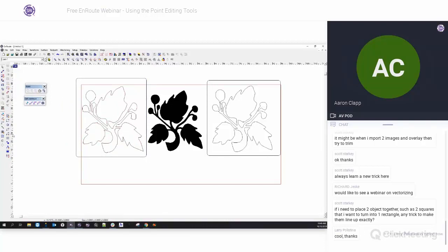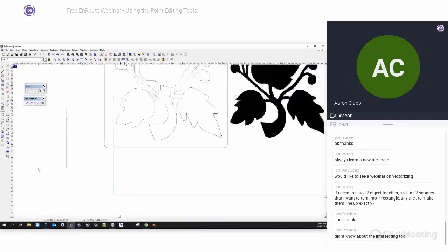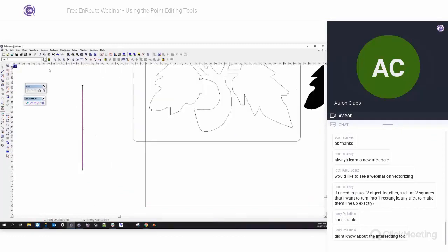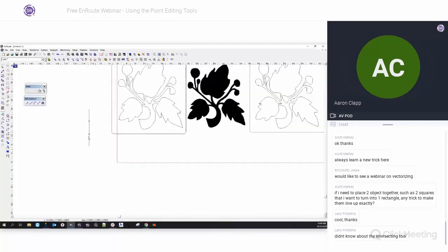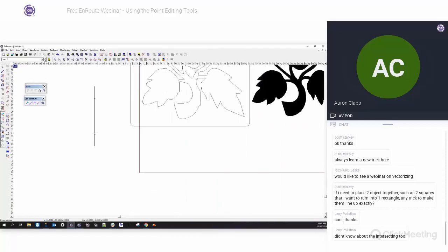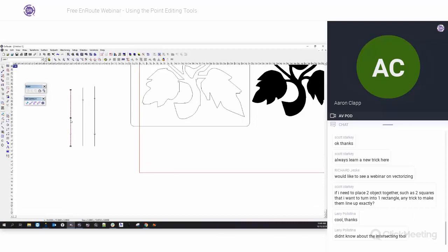Oh, and then the last one, there is another instance where this might happen. So if we have a line, just to say a line like this, I'm going to copy it and then paste it right on top of each other. And then I'm going to change the direction of one of them. This will happen very frequently. So anytime you have an open contour, you are only going to see one chevron. So you should only see, like in this line, no matter what direction I create this line in, I should only see one chevron. And in this line, I have one line, so I have one chevron, and that tells me what direction it's going in. Same here, it's going the opposite direction.